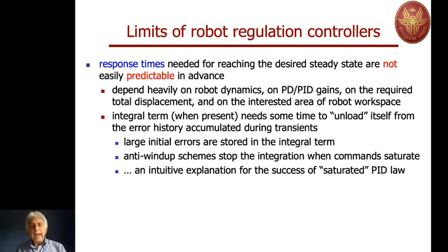So there are anti-wind-up schemes that avoid this process in an automatic way. By the way, the fact that the integral term is too loaded, and this may at least slow down convergence, if not bear at all asymptotic stability, is also an intuitive explanation for the success of the saturated version of the PID law. In fact, the saturation is only on the integral term.